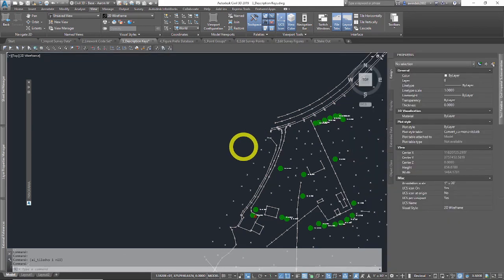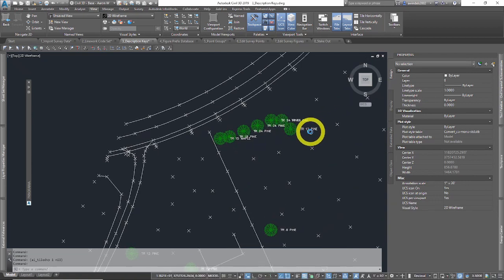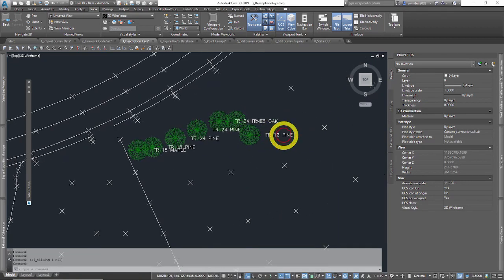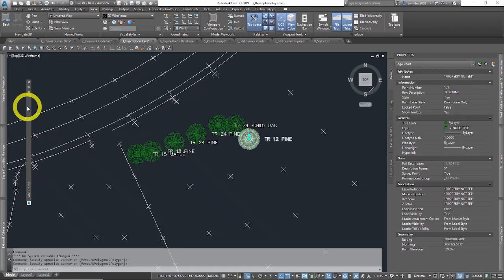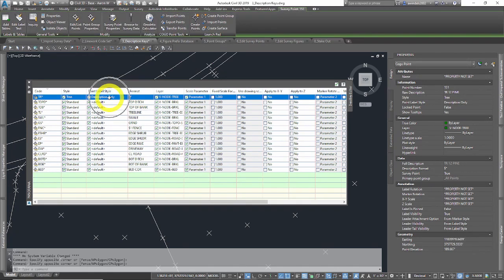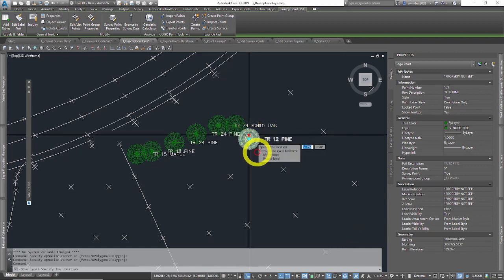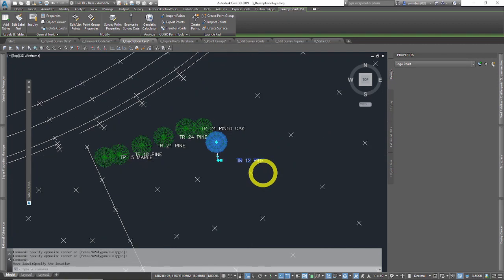That might be easier than just isolating the trees. So it reapplied them all, and of course the only change I made was adding a point label style called description to only the trees. That's all I did. Right here in my description keys, okay? And that's what happened. Now these same labels can be moved out as leaders, etc.